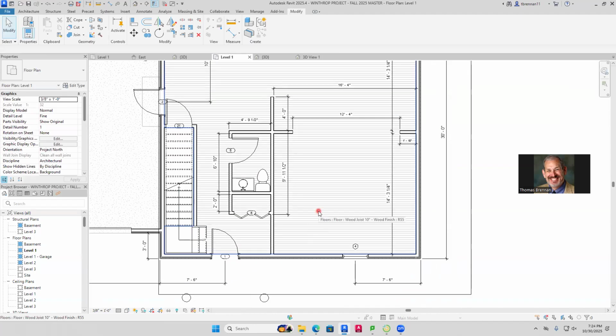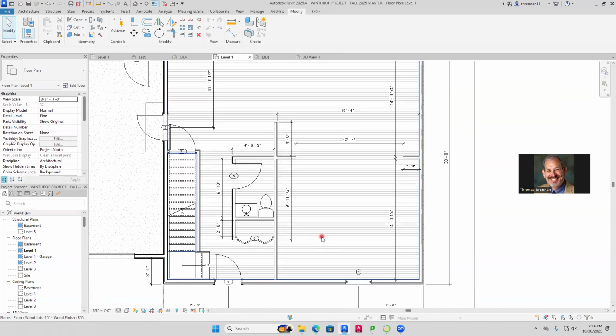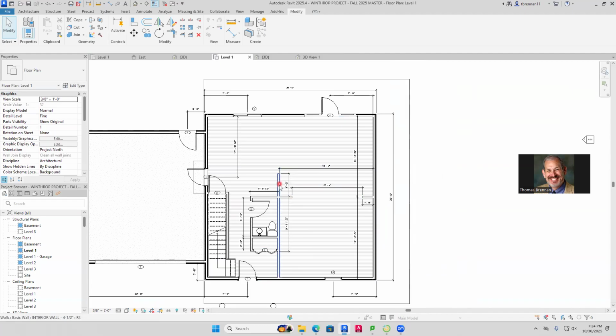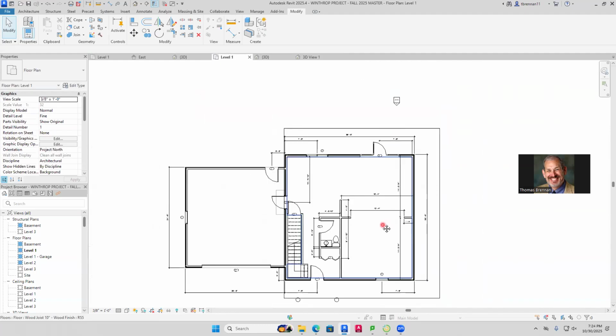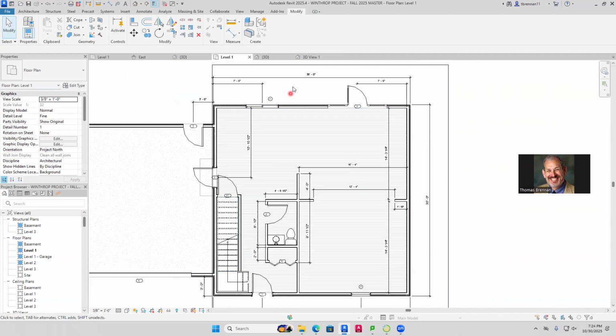Okay, now we're going to do one more thing here because we can. Now, this vertical wall right here is 16 feet 4 off of this other wall. You could just run it about halfway through so it overlaps this one, but it goes past this wall by 4 feet. So we'll deal with that. It's 16 foot 4. Let's go ahead and put that in now.